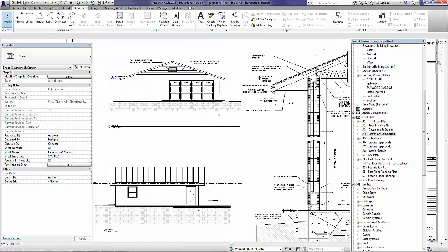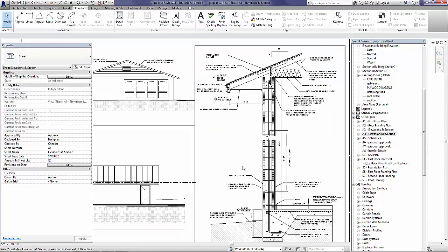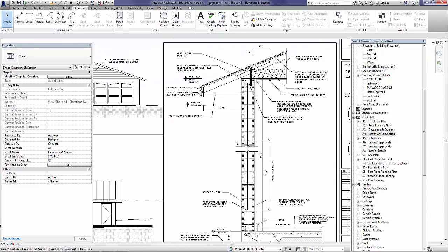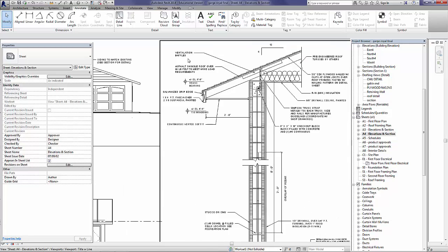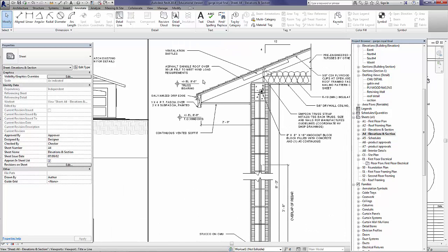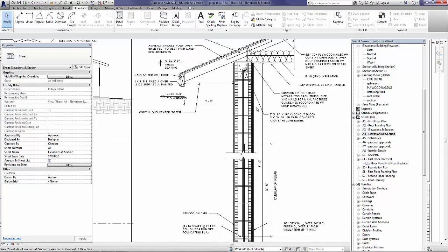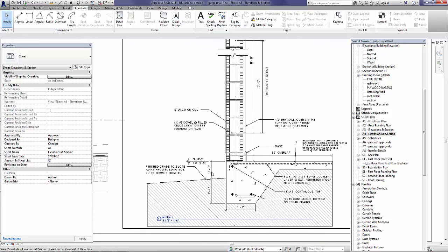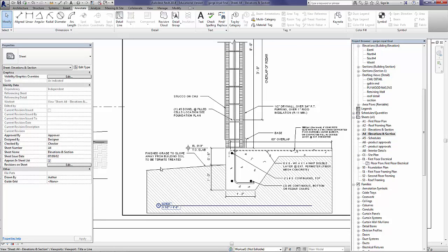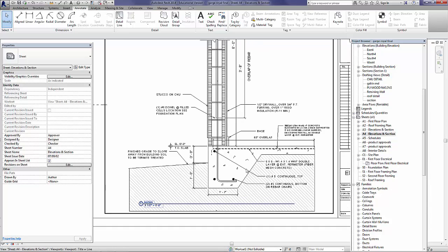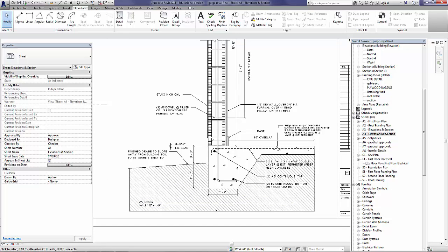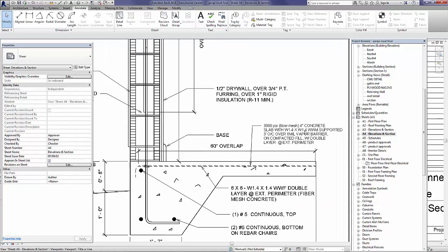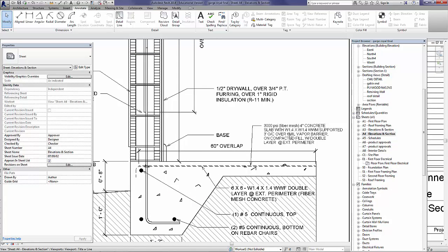As you guys can see here, we've got the same thing for the other elevations, as well as the ventilation baffles. We can see the different things called for here, knockout block, things like that. And you can see how again the finish grade is away from the building, and also the different welded wire mesh here, and just how it's supported and things like that.